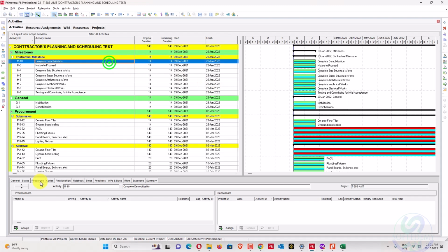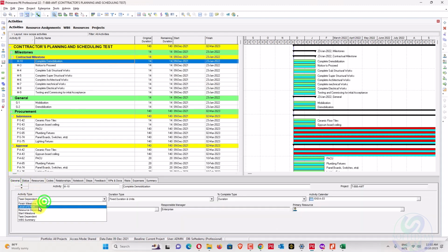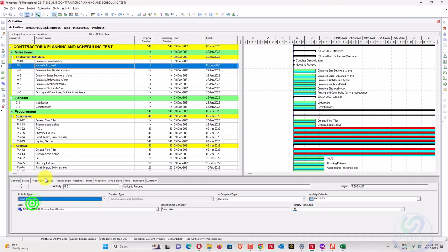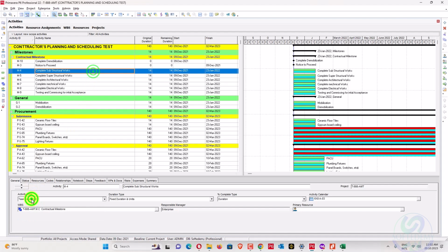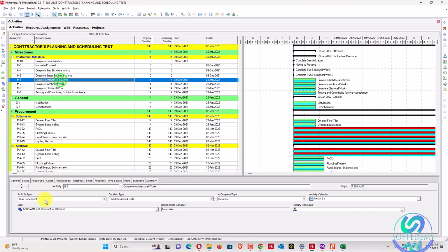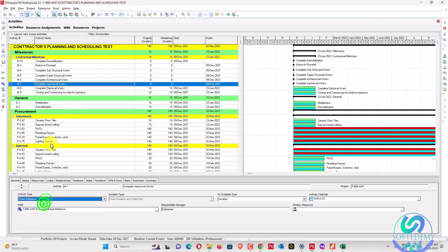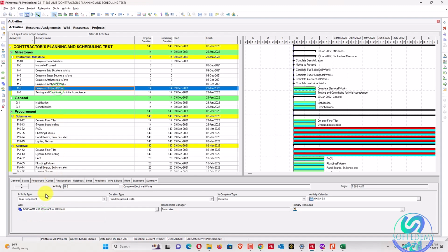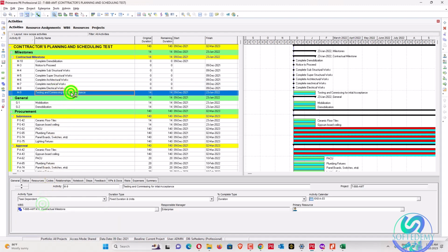Okay, these milestones are added: this is the start milestone, and this one is the finish milestone. You can also add a column here to identify this one. Okay, finish milestone. I will link all my activities to create the schedule. The schedule hasn't been done. Only resources have been loaded, and all other work has been done, but our project scheduling has not. That is CPM scheduling, and that one is basic.